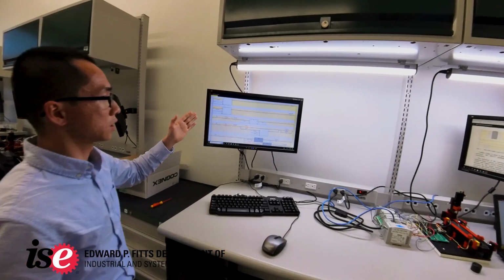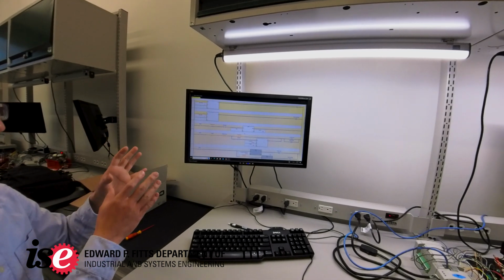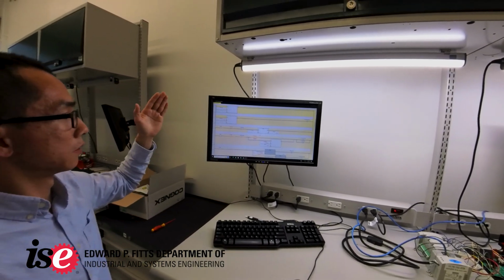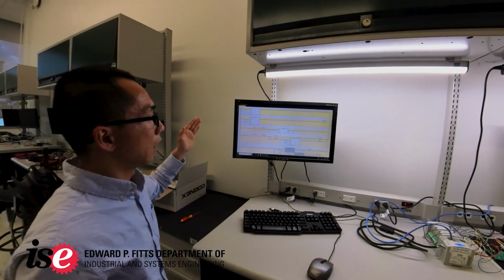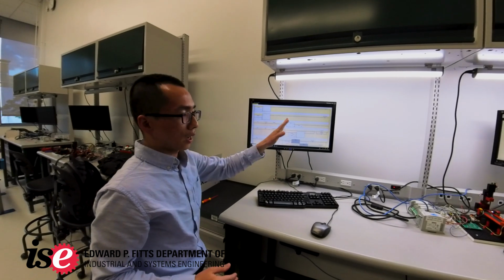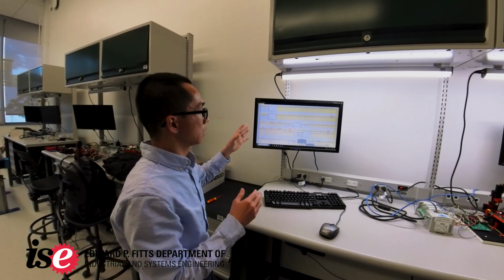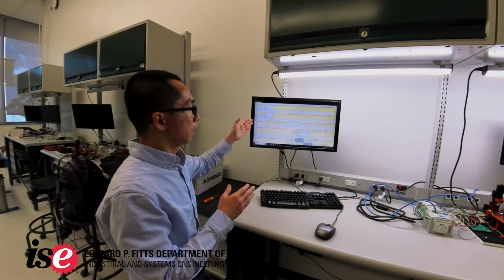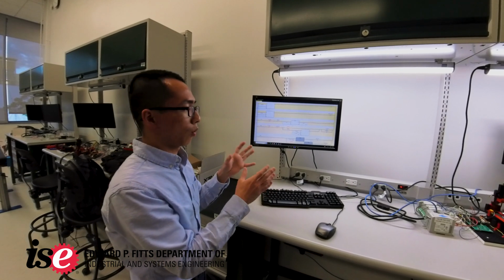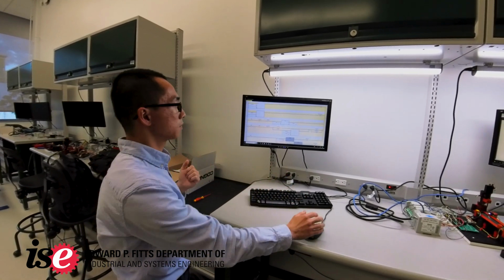And the next one is how we control the speed of the conveyor belt. When the conveyor belt is enabled at the default speed, we won't stop it. But when we change the speed of the conveyor belt to slow speed, we will stop the conveyor belt for 2 seconds and run it for another 1 second. So the total cycle is 3 seconds.